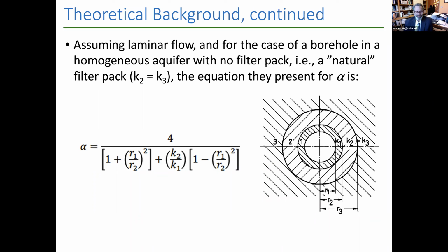And so it turns out, I think theoretically, we would have gotten the same results if we'd done them at a pore water velocity of 1 meter per day or 100 meters per day or 10 meters per day, because the relative effects of these different materials and their permeability is going to be the same. So the experiment would go faster or slower, but ultimately we would get to the same final point.